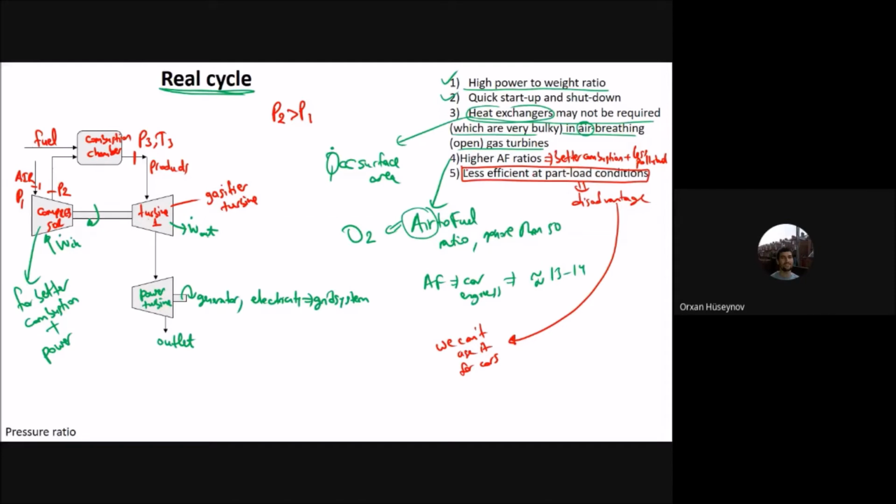One more advantage that I can add here is that as you start the system, you have the spark plug here. The spark plug is used for ignition, but once the ignition happens, it continues. You don't need to start the ignition again and again. For example, in a car engine, the spark plug sparks the mixture each time. But here you don't need it. As the combustion starts, it goes on continuously. This is a very big advantage, and it is the reason the system is used. The advantages are the reasons that are making the system famous.